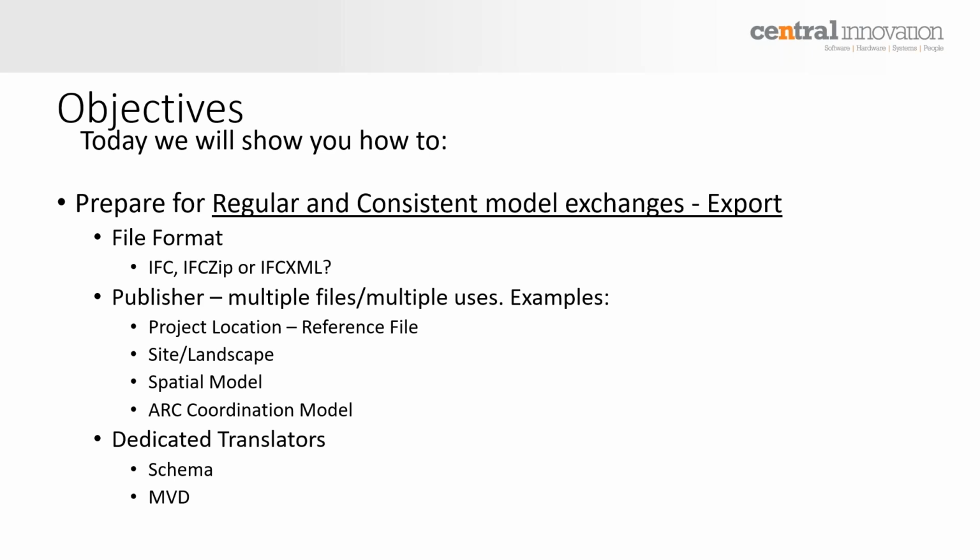Today we're going to focus on 3 main things, all of them based on the idea of making sure that you have regular and consistent model exchanges when you're exporting your files from ArchiCAD. And that depends on mainly 3 things. The kind of file format you're going to export. In IFC, the IFC itself comes in different flavors: IFC, IFCZip, or a compressed mode of the IFC, and the IFCXML.